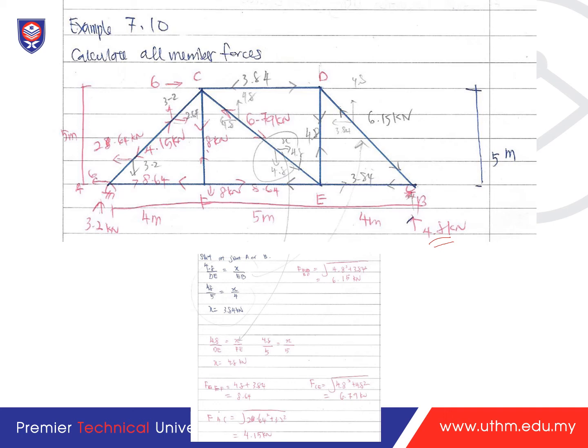So you can see that here we have a force towards EB, and here we have a force diagonally, FBD. For these forces, it will have two components. The 4.8 is going upward, and because this is in equilibrium, total Fy equals 0 and total Fx equals 0 for each joint. So since this is going upward, there is a force here going downwards to keep the total Fy in equilibrium. Here is 4.8, so here will also be 4.8, going downward.